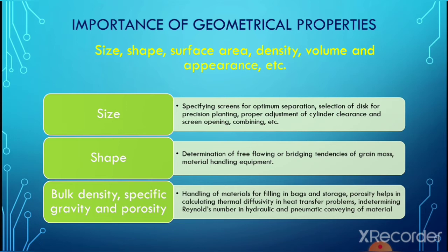Then bulk density, specific gravity and porosity. Handling of materials for filling in bags and storage. Porosity helps in calculating thermal diffusivity in heat transfer problems, in determining Reynolds number in hydraulic and pneumatic conveying of material.